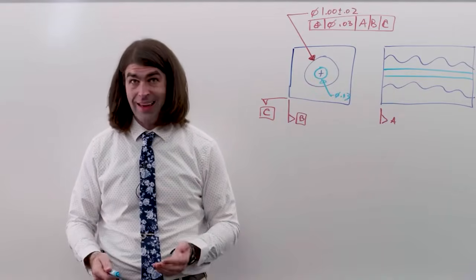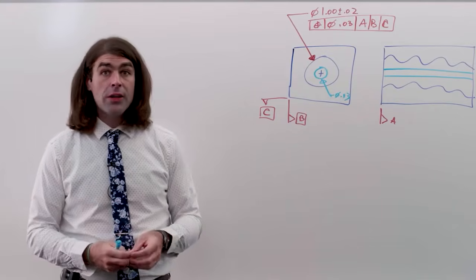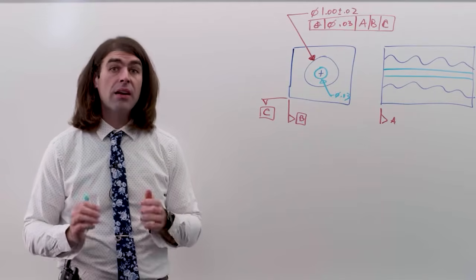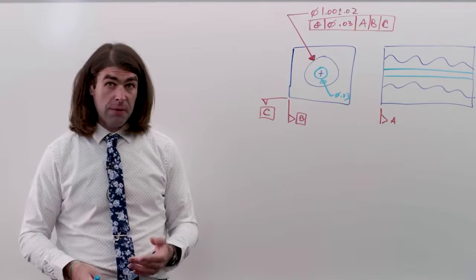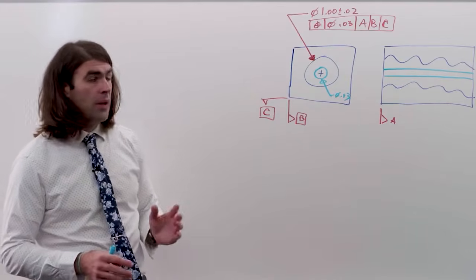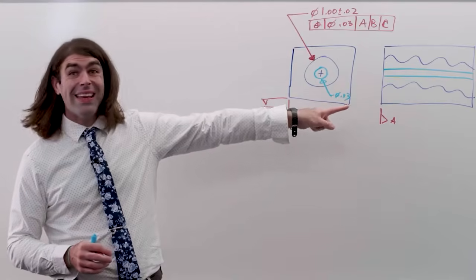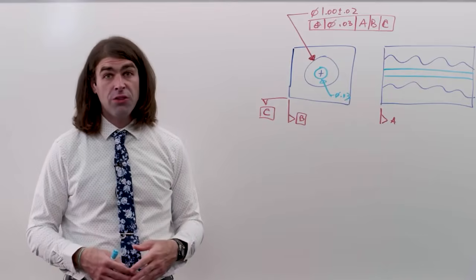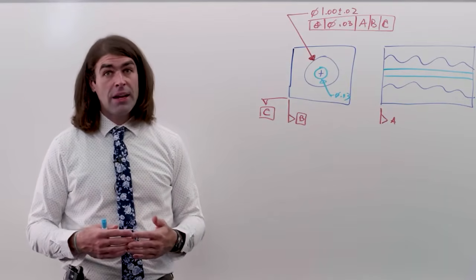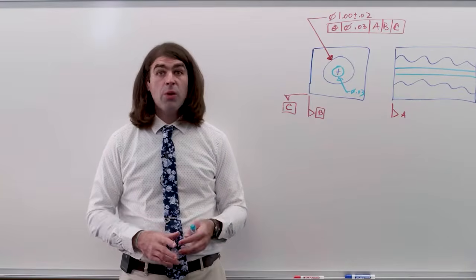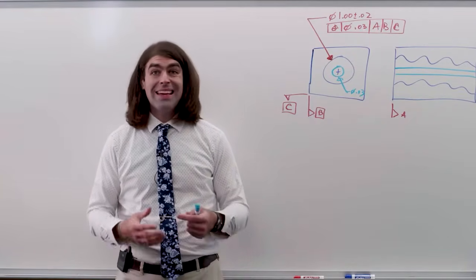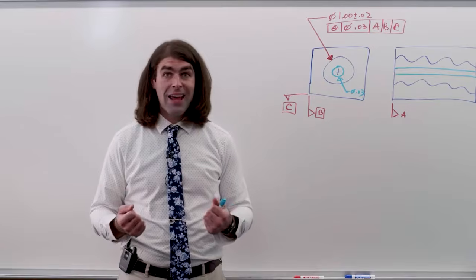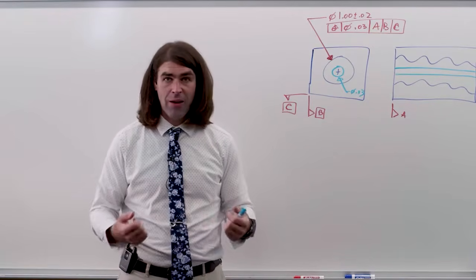So what are we controlling exactly? Well, for a hole, we're controlling the axis of the unrelated actual mating envelope. What does that all mean? Well, in order to figure out where the axis of this hole is, we need to decide how we're going to get the axis. And the ASME standard, how we're going to do it, is by using the actual mating envelope, which, for right now, we're going to say is outside the material.